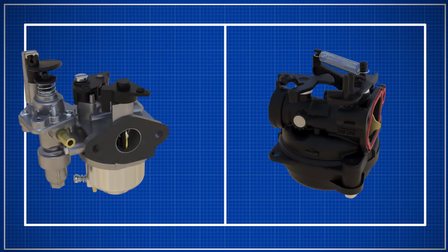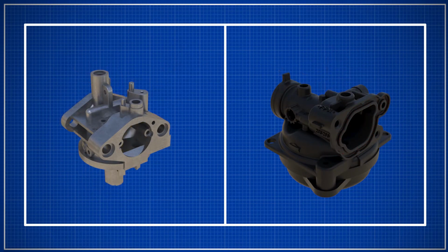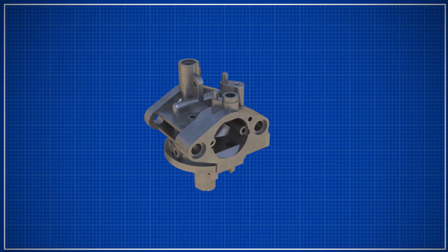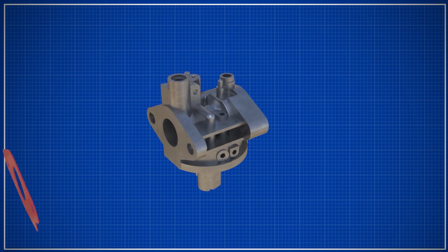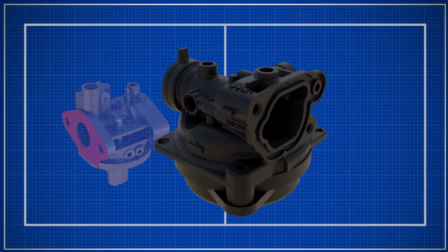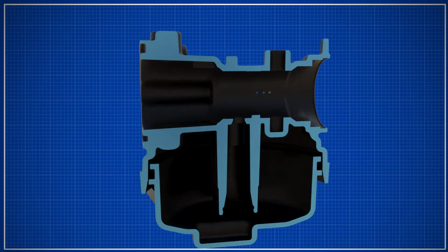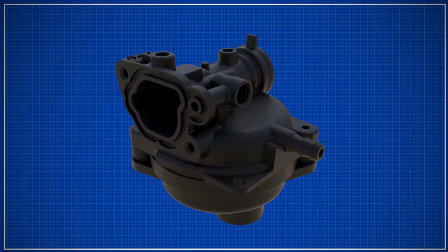Fundamental carburetor construction. To better understand how the carburetor operates, we will build a model. We will add the necessary components in order until we have a carburetor that will let an engine operate. The foundation of all carburetors is the body. In this example, our basic carburetor body will have some of the core components. These core components are a mounting flange to attach the carburetor to an engine. It also has a pathway from front to back for airflow. Lastly, it has a fuel inlet port, which will be used later.